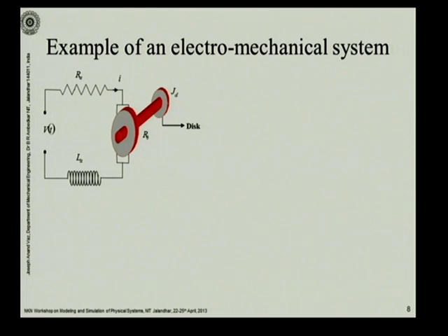It is a system of, here you have a permanent magnet DC motor, and there is a rotor which is shown, you can see. This is a rotor and this is the disc of the rotor, and connected to this rotor are the armature brushes. Okay. So here on the commutator of this, here you have some armature brushes, and it's a winding.